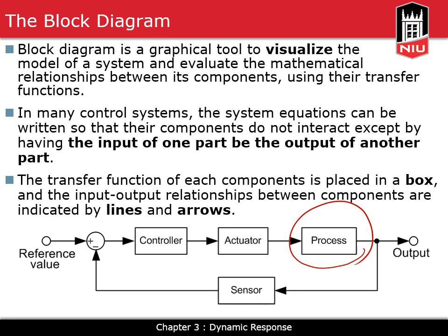We said earlier, if we do open loop control, there is no need for any measurements, but that is not functional most of the time. We are talking about feedback control in this course. So we need to measure the output. That is the variable that's important for us. We do that through a sensor. We measure the output variable and feed that back to the input side.